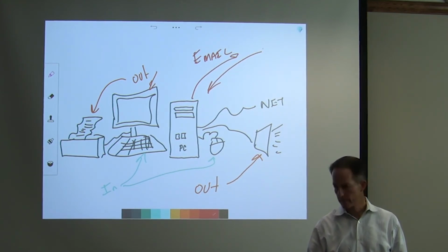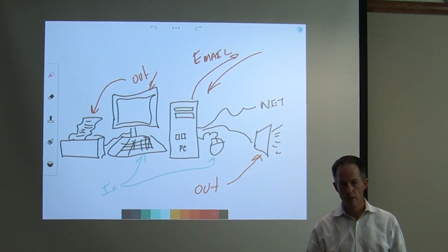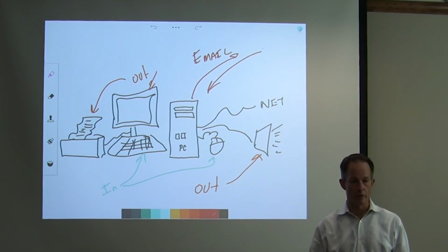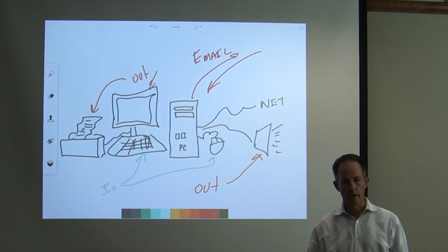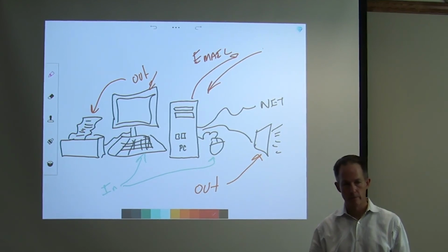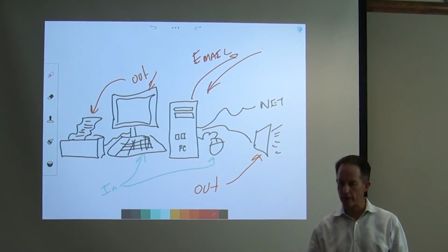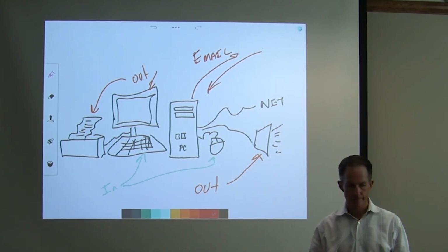They're not twins. Those dorms use a whole lot of cooling, and evaporative cooling set up right can work year round, without any doors open, things like that. We don't have any access to windows or anything like that. No, you don't need to. It would still function just like your normal air conditioning with chilled water. It's just that then you would use evap cooling or indirect evap to cool it. It's in the air handler. You're not injecting moist air. It depends if it's direct or indirect. What we have so far is all direct.